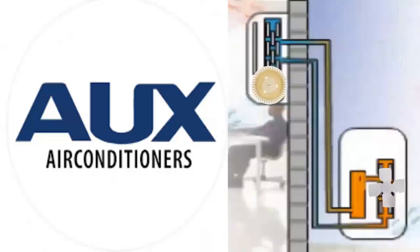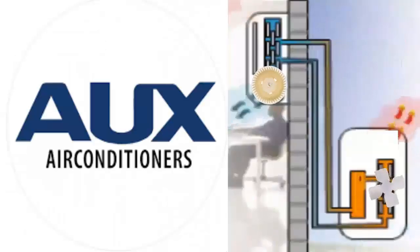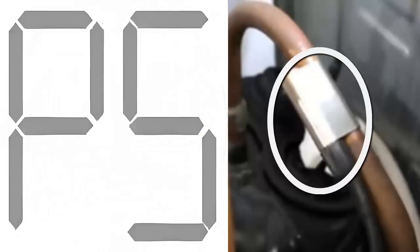Error codes F4 and P5. These indicate a problem with the sensor located at the compressor discharge pipe, which measures the temperature of the freshly compressed gas.